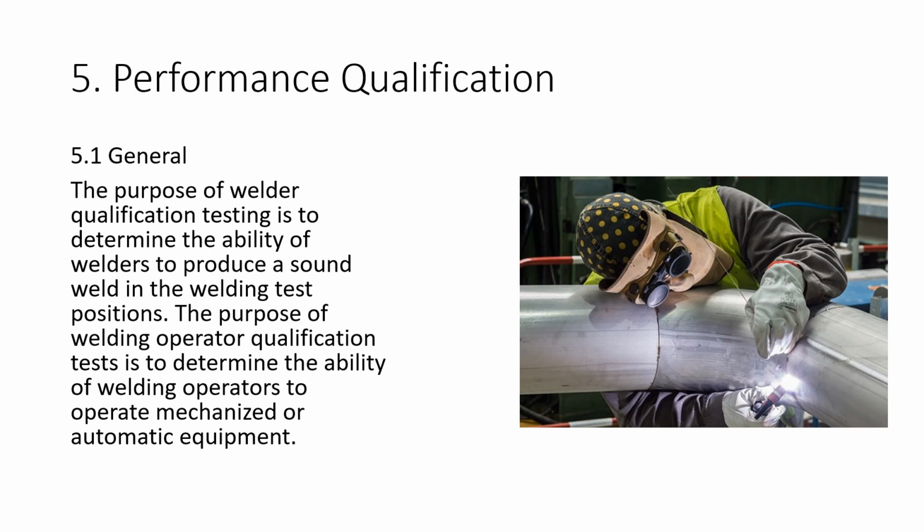And this is, if you use this document as your welding code, like I said, if you've got some kind of situation where you're making a product that doesn't fall into another welding code, and your client wants a welding procedure, a PQR, and welder test qualification records, this is what we're doing. And this is super similar to ASME Section 9.